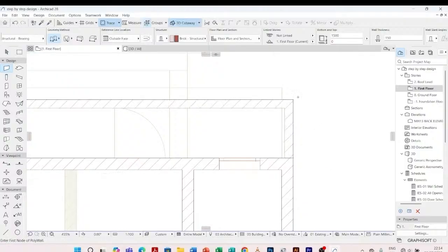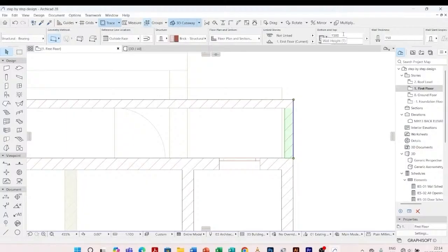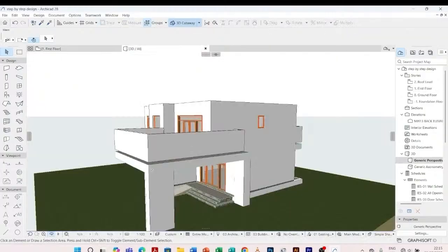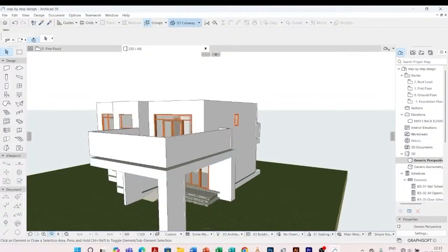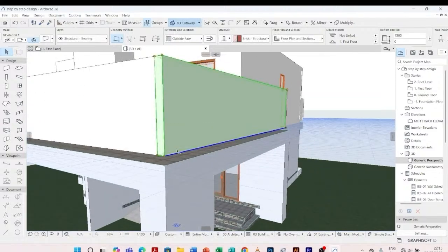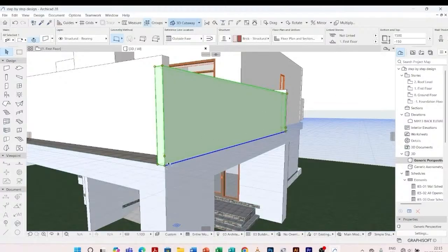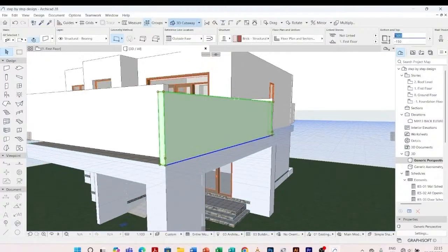up to there. So we did not set the height of the wall. Here the wall height is 1500, but I didn't want to set because I wanted we do it in 3D so that we can get a proper height. So when I click on this wall, it is starting at 0, but remember our slab is a bit down, so I'll Ctrl D, I move this wall down at -50, then I will give it a height of 200.